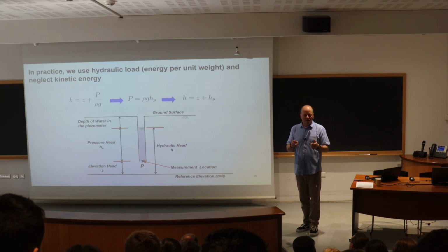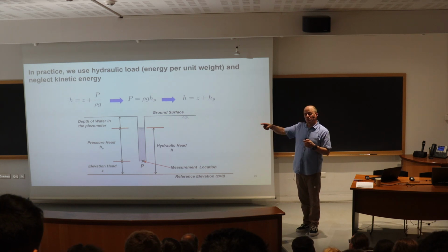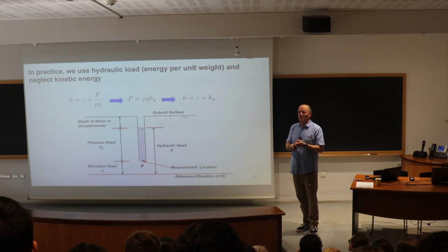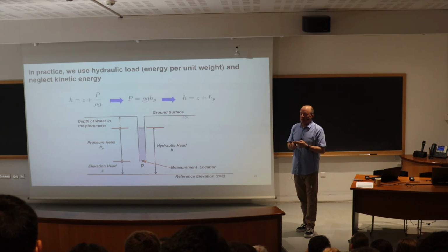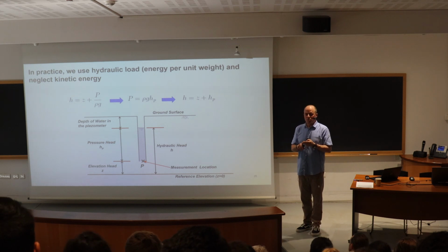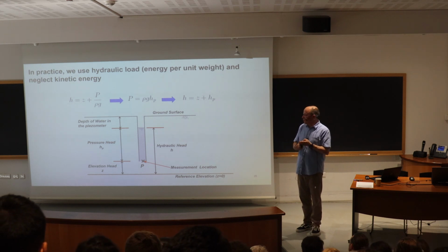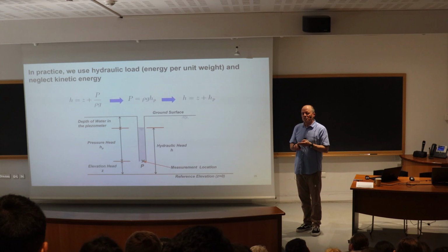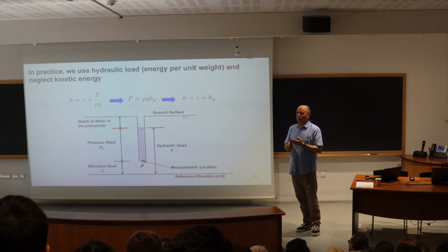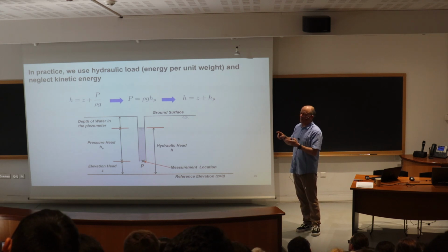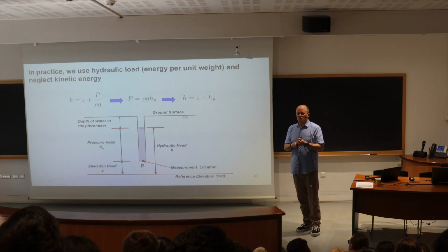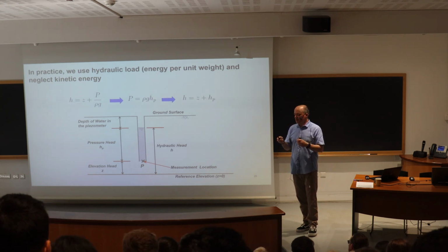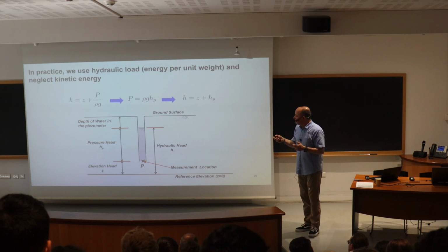It's not always the case. If you're interested in, say, saltwater intrusion, like in coastal areas, you're going to have variable density of the fluid. If you're interested in thermal applications, geothermal, the density of the fluid will not be constant, and also the viscosity of the fluid will not be constant. So this simplification you should not make. You should not work with a reference fluid, because the fluid has variable density and potentially viscosity.